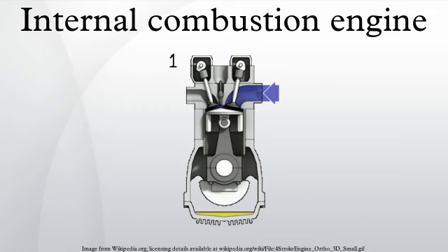Once the available energy has been removed, the remaining hot gases are vented and this allows the piston to return to its previous position. The piston can then proceed to the next phase of its cycle, which varies between engines. Any heat that is not translated into work is normally considered a waste product and is removed from the engine either by an air or liquid cooling system. Internal combustion engines are primarily heat engines, and as such their theoretical efficiency can be calculated by idealized thermodynamic cycles. The efficiency of a theoretical cycle cannot exceed that of the Carnot cycle, whose efficiency is determined by the difference between the lower and upper operating temperatures of the engine.